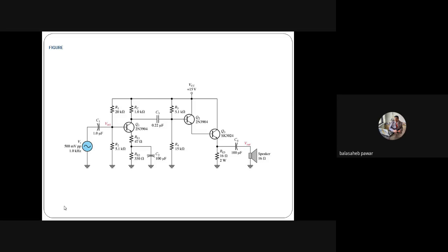Okay, this amplifier does not support 100 millivolt peak to peak or below. Above 100 millivolt, we are getting the output, so we will call it a conventional amplifier, right? Now, since it will not support that, I just took that as an example; practically we will identify the actual limit. Suppose the signal is 100 millivolt peak to peak and does not get processed by this first stage. Then what to do?